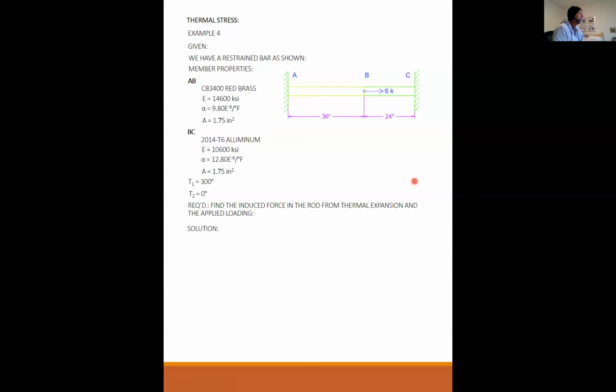Okay, I got several no's. That is correct. The force in AB will not be the same as the force in BC because you have to maintain equilibrium at joint B. If you did a free body diagram of joint B, there's a load applied to it, so the restraining forces cannot be equal to each other with this applied load on there.